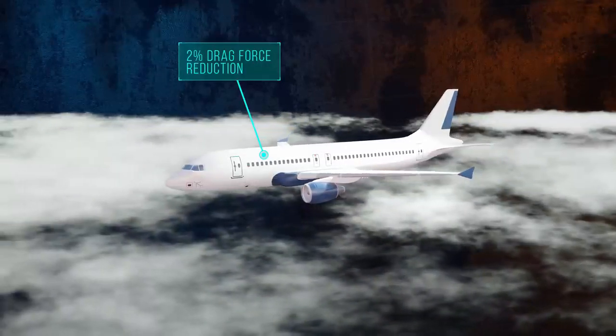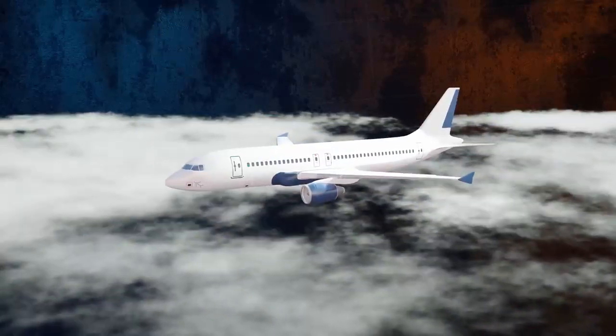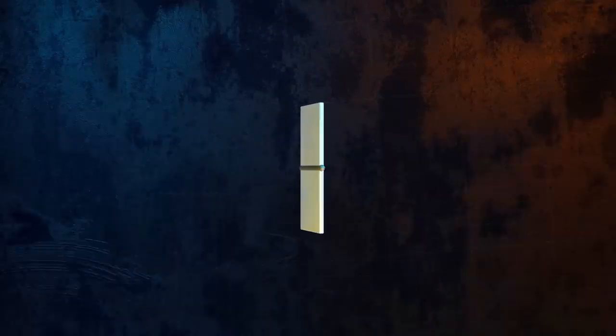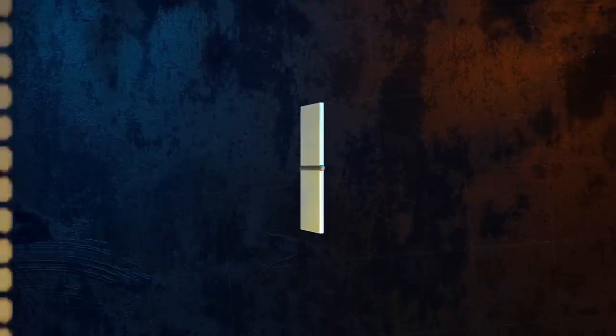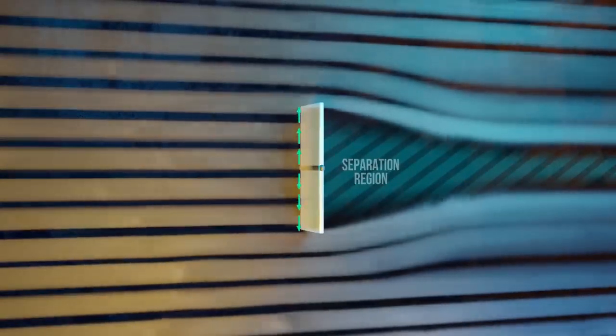We've seen that the magnitude of pressure and friction drag depends on the geometry of a body relative to the direction of flow. The most obvious example of this is a flat plate. If we position the plate at 90 degrees to the flow, it is a blunt body. Flow separates easily, creating a separation region, and so the pressure drag is large. But the friction drag is almost zero, since shear stresses aren't aligned with the drag direction.